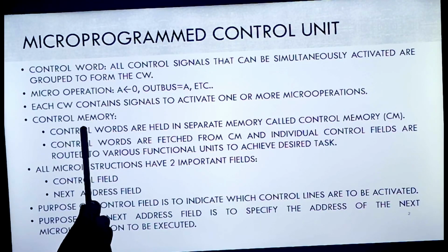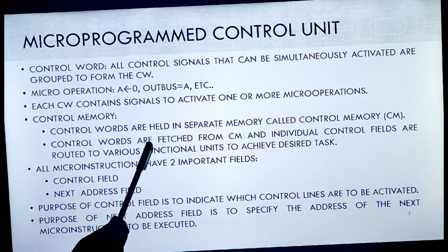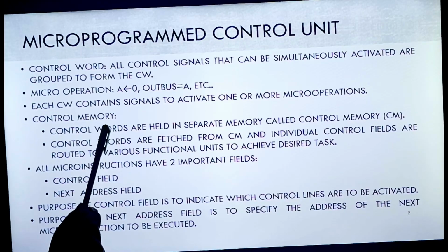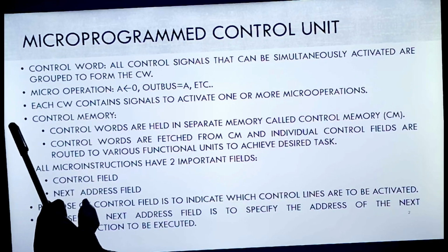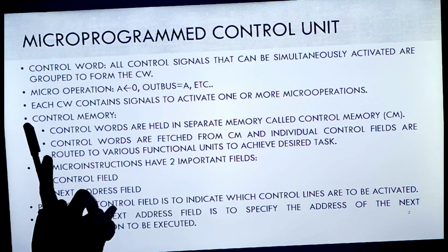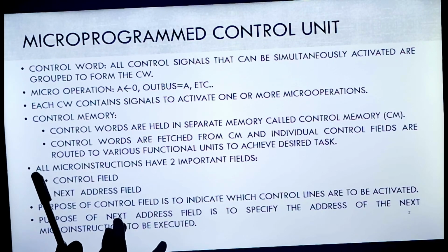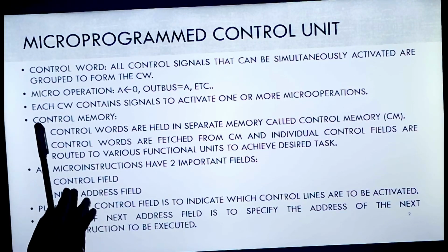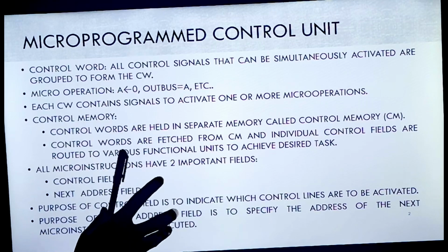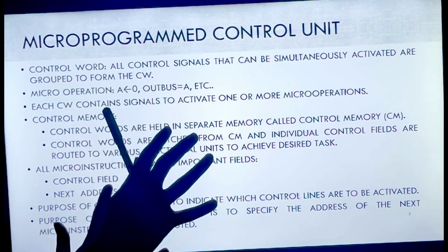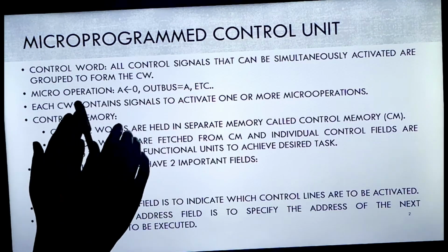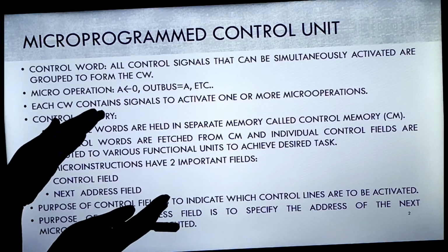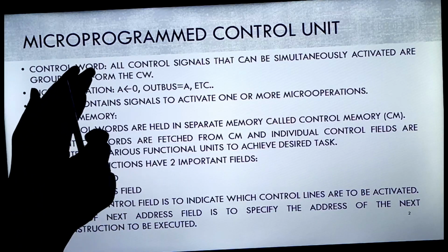Now in the microprogrammed approach, there is a twist. We won't follow the same approach here. Initially we identify how many control signals I need throughout the operation. We know for Booth's algorithm I need 10 control signals, C0 to C9. Now, unlike our hardware approach, here I will generate all these control signals first, and then I will store them somewhere. So I will have all the 10 control signals stored somewhere, and whenever necessary I will just activate the